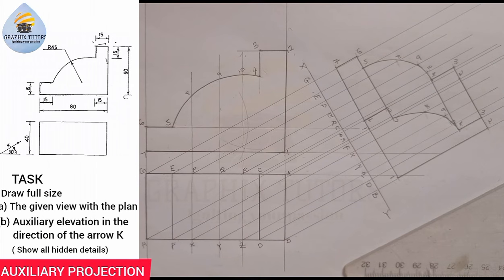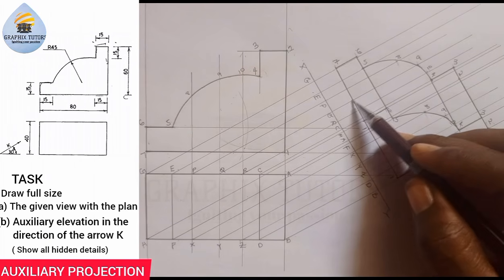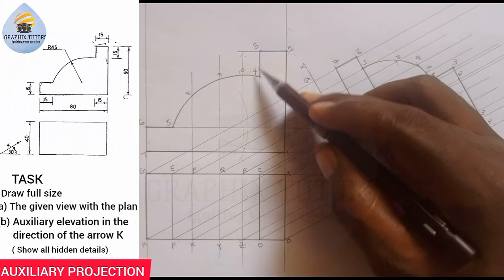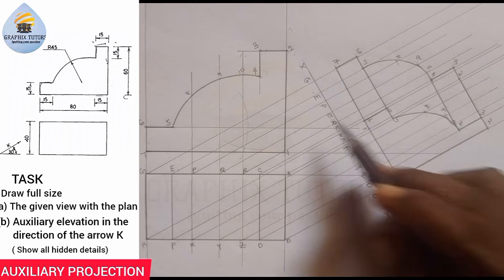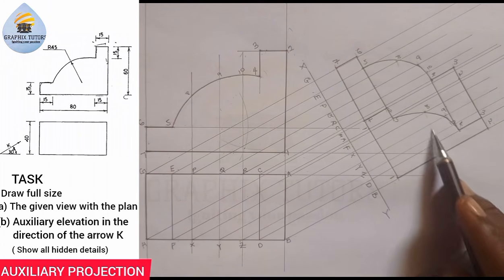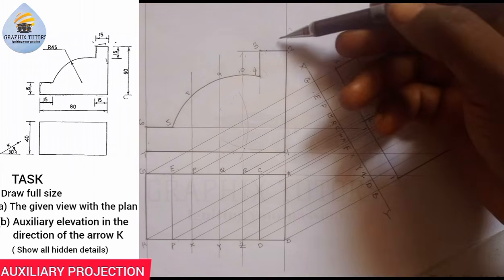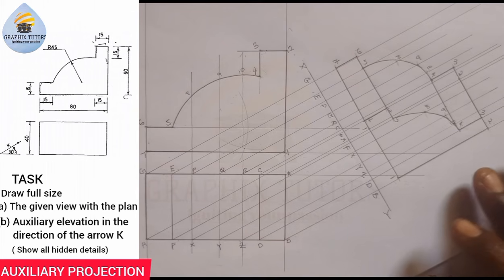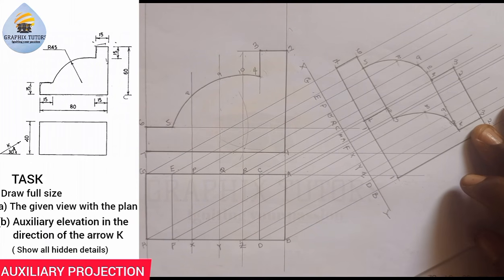You can see that. So this is what we have here. We brought out that shape because when you look from this side, you see a thickness here. This is the thickness you're seeing. You see another thickness here. And this shape, looking from the side, is what we have here from the top. Although you will not see that from the top. So this is the auxiliary elevation that we're told to draw.